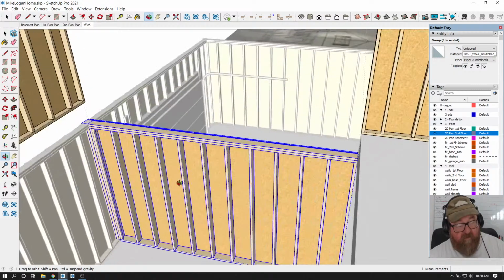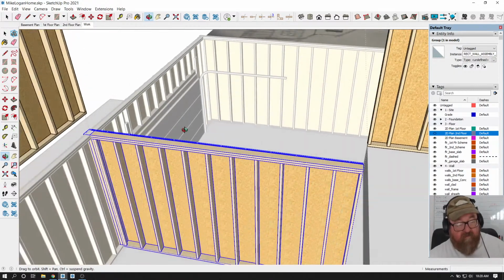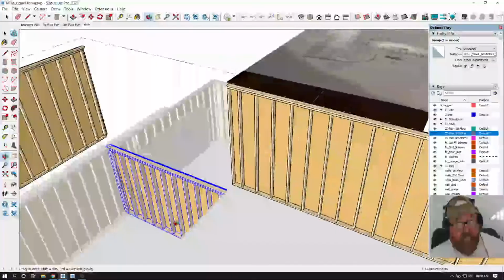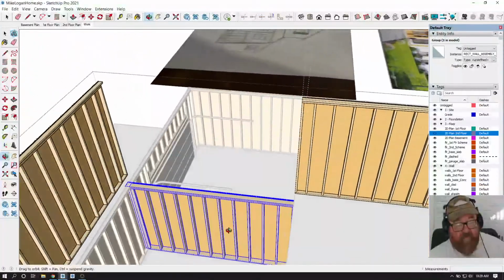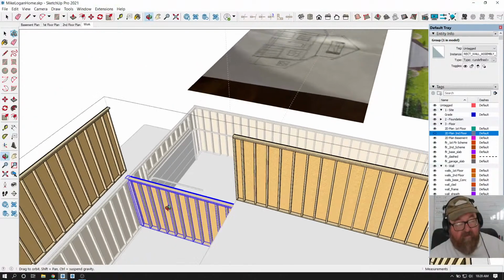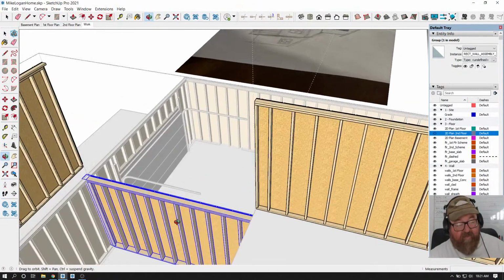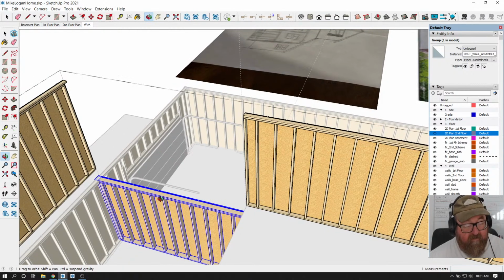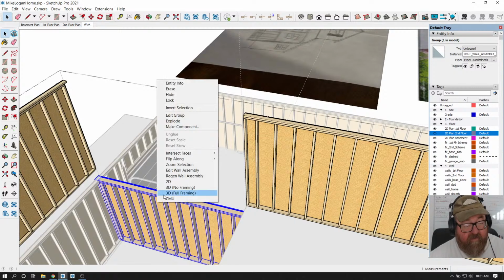So when you're building a wall like that, we're probably going to have to use those LSLs, the laminated structural, the studs that are almost like, they're not quite LVL density, but they're manufactured, they're engineered studs that allow you to create these really tall walls. I mean, I've built 20-foot walls before with them, so I know this is going to work. Edit.